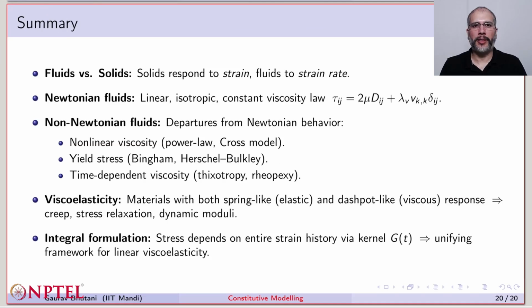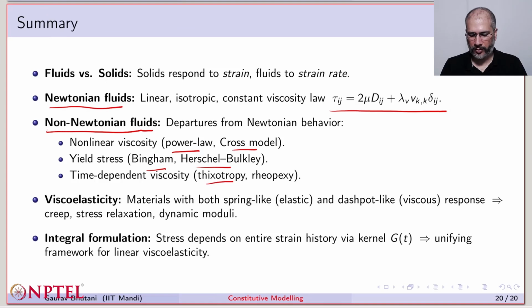And finally, summarizing today's lecture, we started our discussion with the definition of the behavior of fluids, where we said that solids respond to strain, whereas fluids respond to the rate of strain. Then we talked about linear isotropic fluids called Newtonian fluids, and we showed this linear isotropic law for fluids. Then we had a discussion on non-Newtonian fluids, where we talked about the power law, Bingham, Herschel-Bulkley, Cross models, and time-dependent viscosity models such as thixotropic and rheopectic fluids.